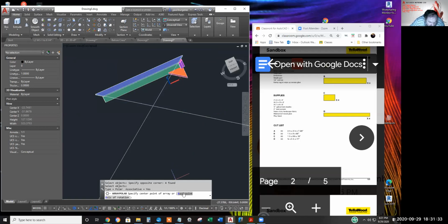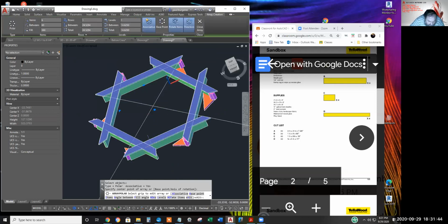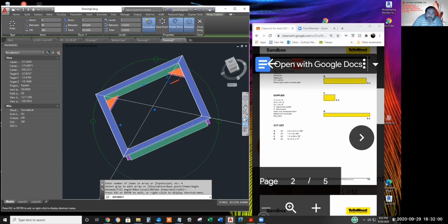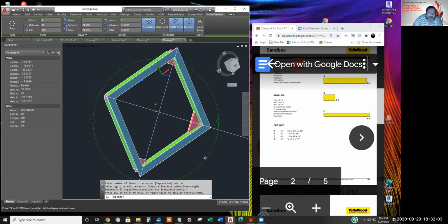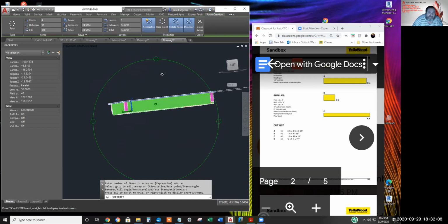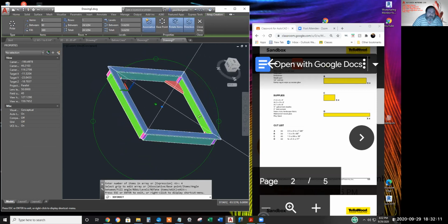Polar array is asking for base point axis of rotation. Now, we'll Osnap at that intersection. And change the items option from 6 to 4. And nothing will go wrong. Now my icons are working. I believe we've got to delete those chalk lines for the polar array procedure.